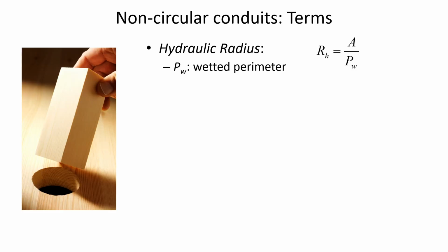And so the adjustment that we make is to think, first of all, in terms of, remember, hydraulic radius, where if it's a circular pipe flowing full, it's as simple as saying diameter divided by 4. But if it's a non-circular conduit, we actually have to calculate the real cross-sectional area and the real wetted perimeter.